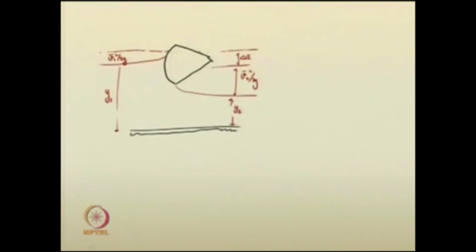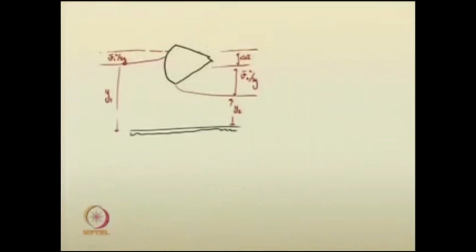Such a structure is a tainter gate. Compared to the sluice gate, it has more span, and it can be used to control large volumes of water also. So, why such underflow structures while designing?